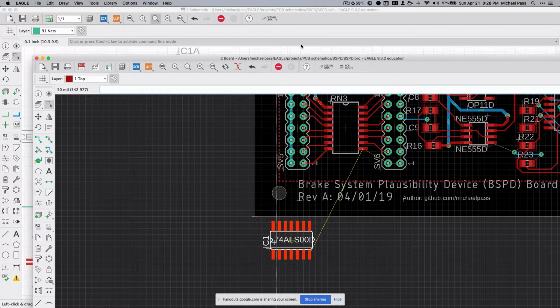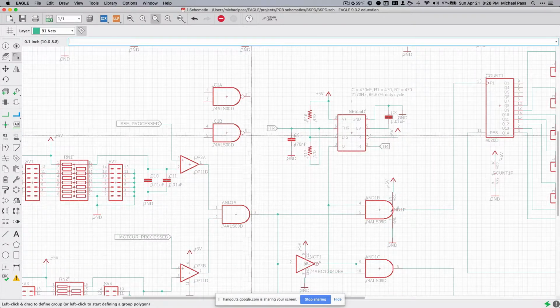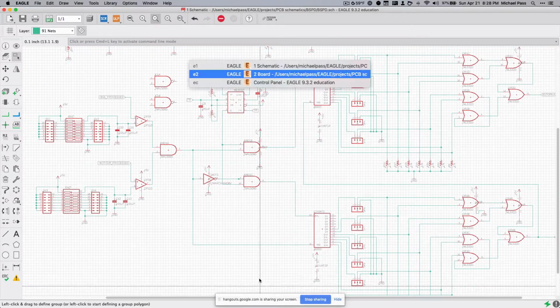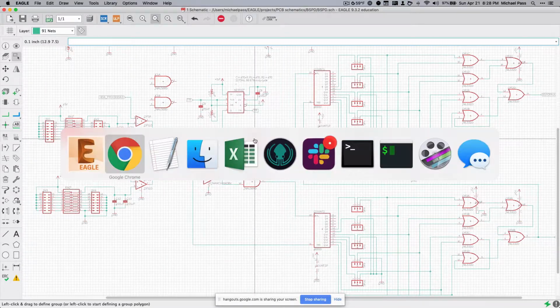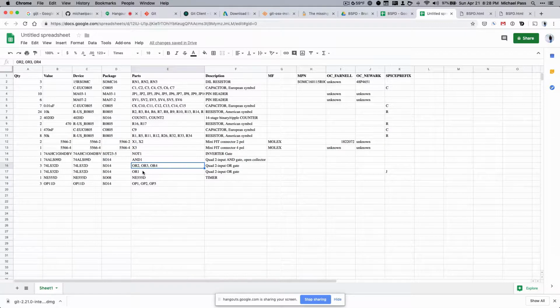part here. So I want to see, in this case, it said that when we were looking at, let's see, it said that there were 3, it's a 4 gate, it's a quad 2 input OR gate, but it says we have, that OR gate's 2, and actually it counts these as 3, so if we were ordering this and we put this into the BOM, these would come across as 3 different devices that we would order if we just use a straight quantity. So it might be the internal logic of EAGLE for generating this, because for this is correct.